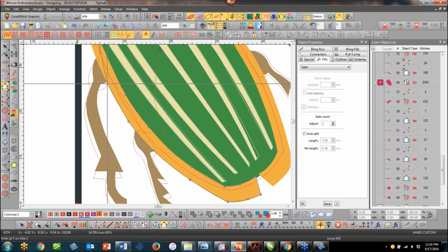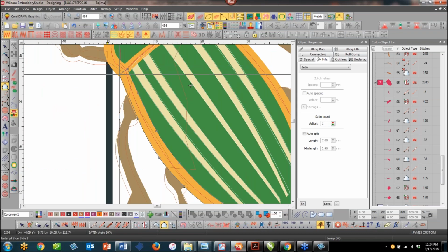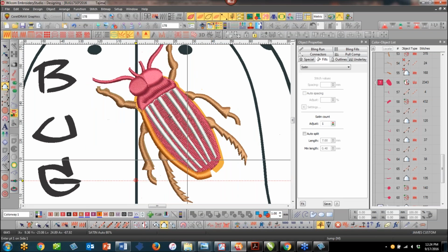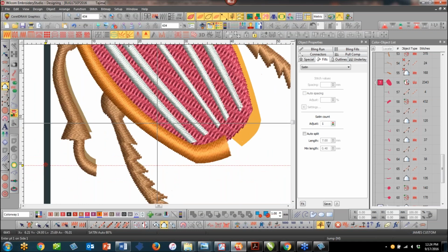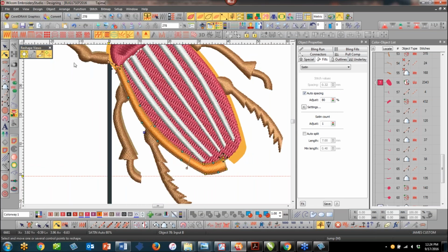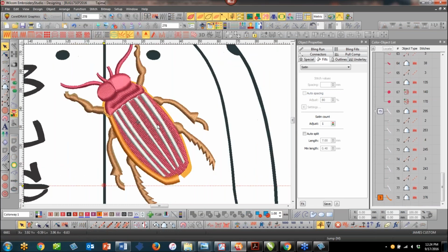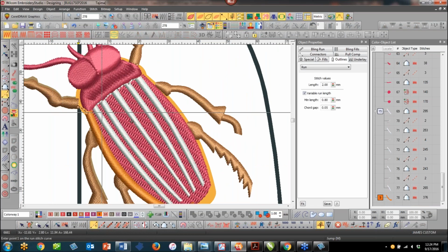Again, the circle or the right mouse button allows you to go in and do fewer points. This is what it looks like. Looks just like that. Okay. If I want to turn those stitches a lot more, I can press H and just press my control key down like this, and I can turn it like this. You see how it forces it to be more of a 90-degree angle here, and definitely makes a difference with this. Running stitch here as I go across.